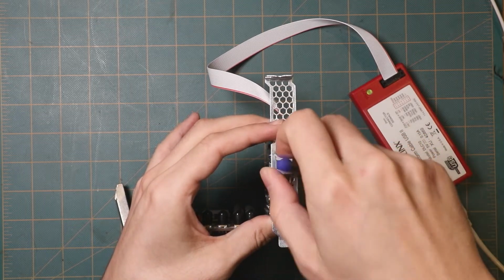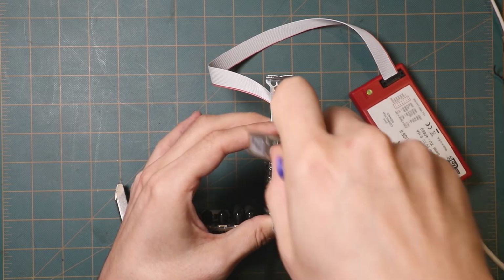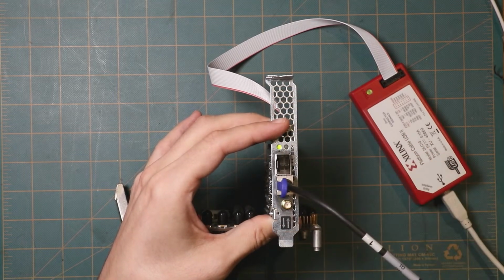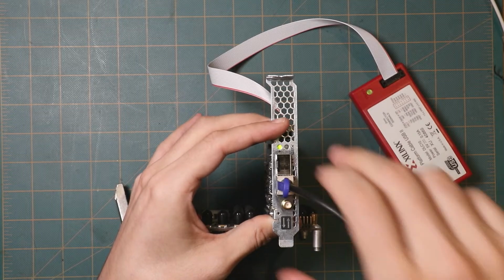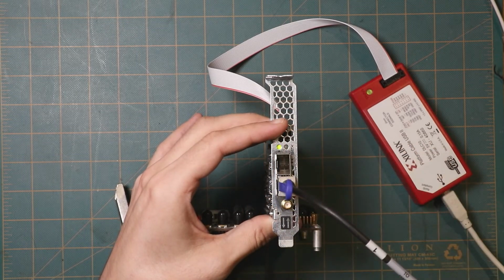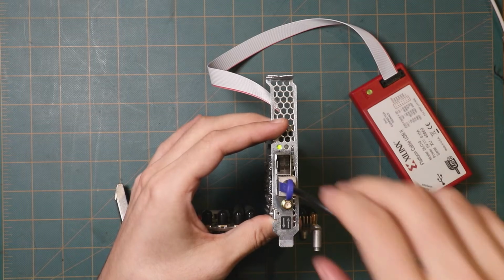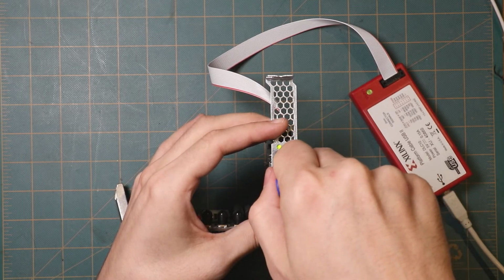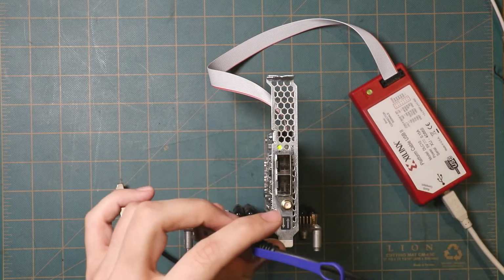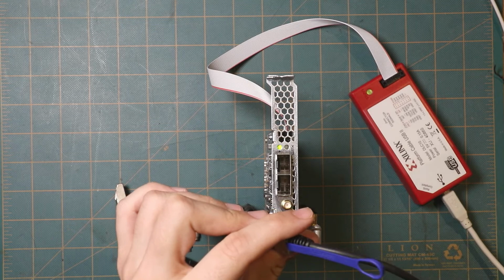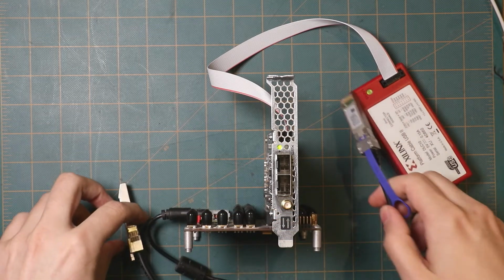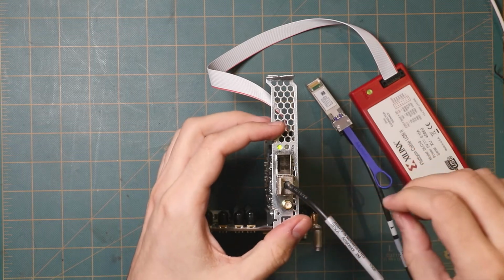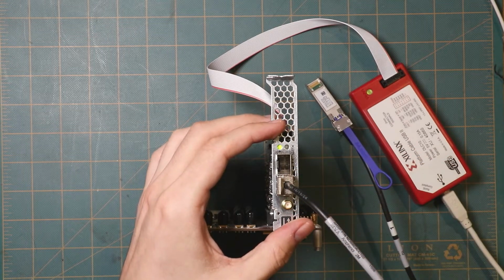I do have a second PHY on here. I don't think it's hooked up to the ILA, so I can't look at what's coming out of that. So far, it seems to be well behaved, aside from leaving the link light on when it's not supposed to be. I'll try this for another few seconds and see if I can get it to do something interesting. Let me try the other NIC, which will have slightly different signal characteristics, and see if that makes a difference.